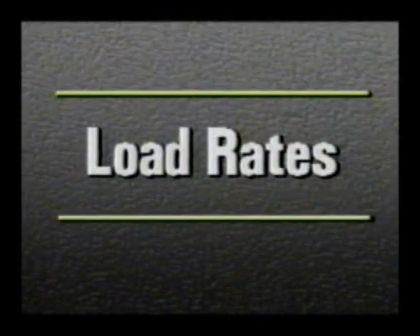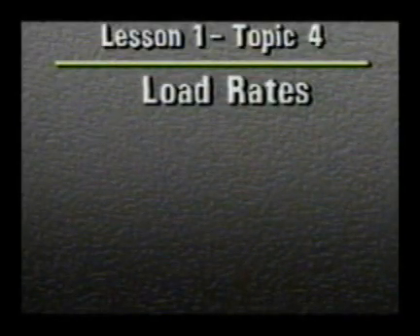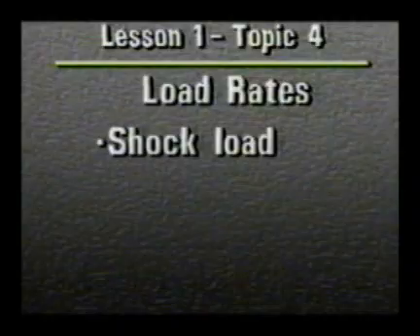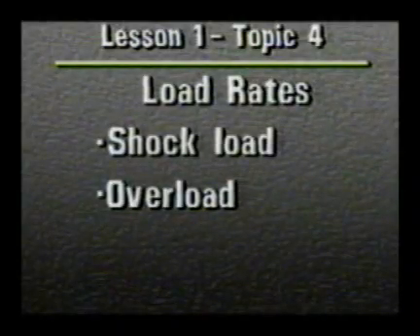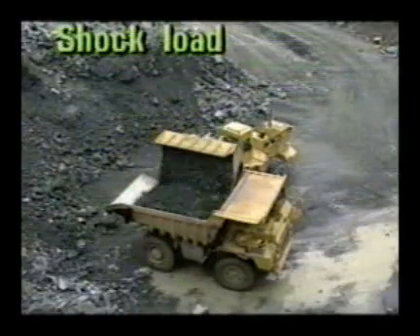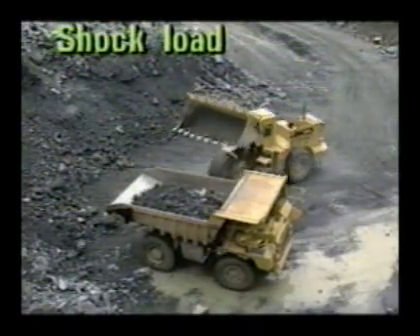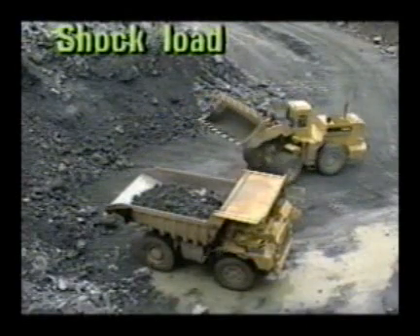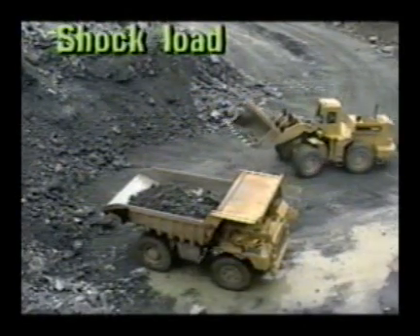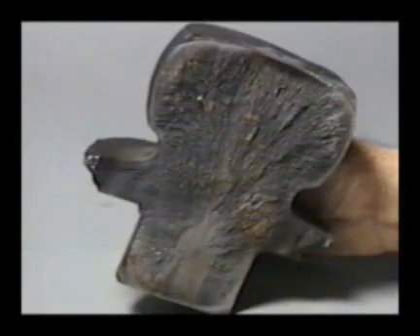The speed with which loading is applied has a great effect on part response and fracture type. There are three basic rates at which loads can be applied: shock load rate, overload rate, and cyclic load rate. Shock load rates are extremely fast single-load applications. These loads can be applied in a fraction of a second, and if severe enough, can cause the part to fracture. The shape of parts that fail due to shock load generally remains unchanged.